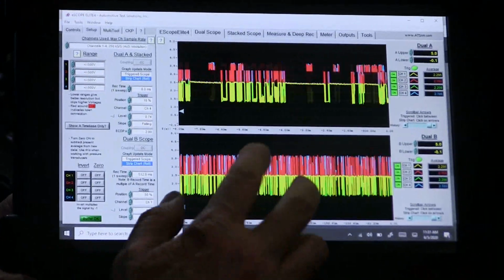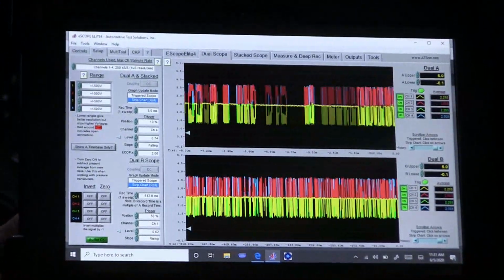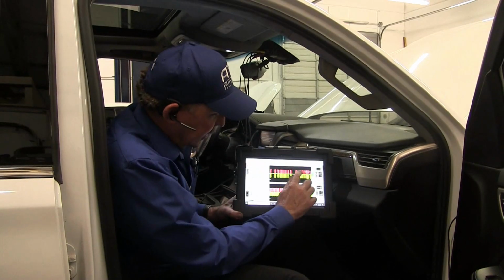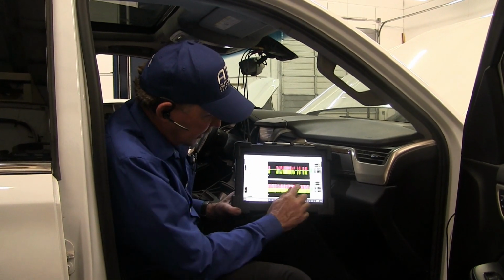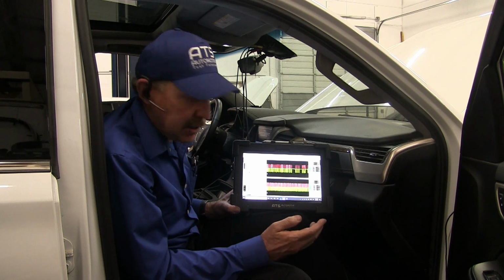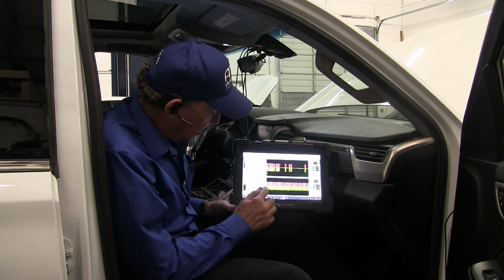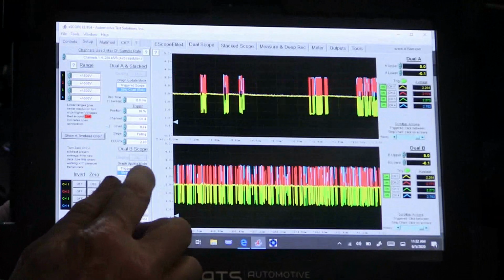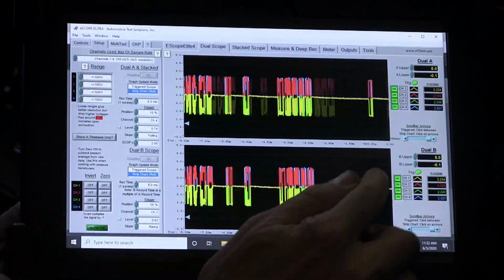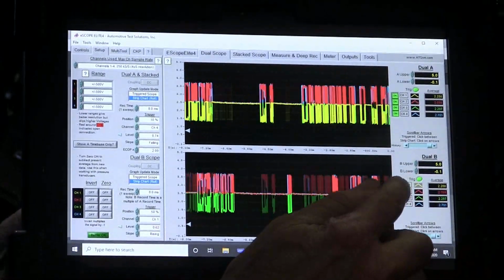First thing we're going to do is come over, and we've got 2 different time bases working here on the scope. This is the CAN high lines, and so is this. There's 2 highs and 2 lows. So let me show you. We're going to change the time on the lower screen to the same as on the top. But now we're going to go ahead and uncover it.